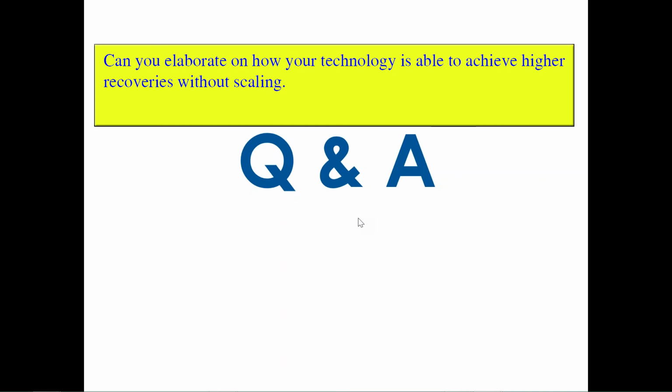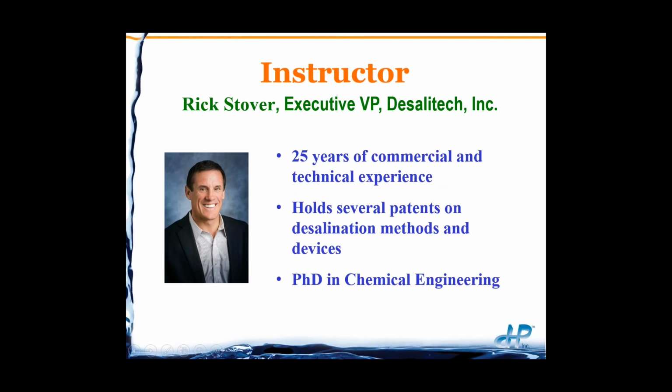And what the Desalitech process is able to do is flush the system without giving precipitation enough time to occur. So we're working inside that induction time. So that's how we're able to trick scaling and we're able to operate at higher recovery rates with supersaturated concentrate. That plus the standard ways to avoid scaling in RO systems, which include use of anti-scalants, pH adjustment, good cross flow, etc.